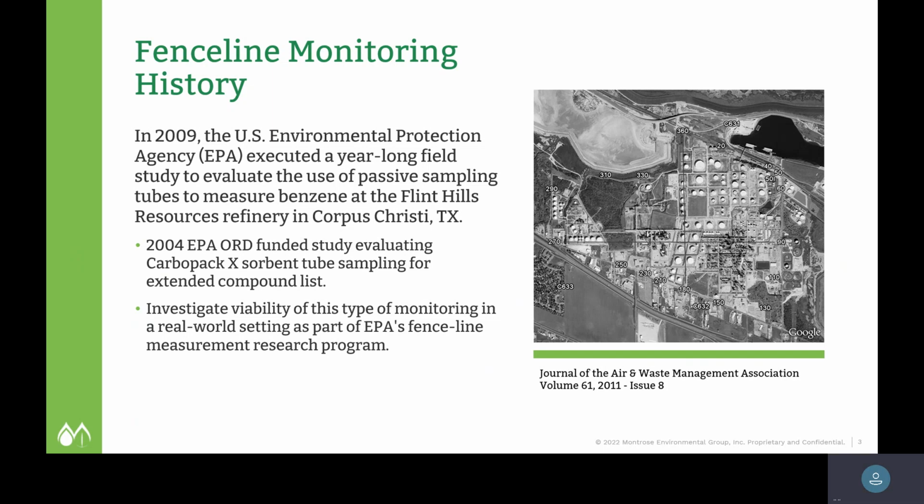One component that they put in place, which is pretty cool, is they deployed these passive samplers side by side with some auto GCs getting speciated benzene data. So you had hour-long averages of benzene speciated data that you would compare to these passive tube results for 14 days. So they deployed it for 14 days. The R squared was 0.86, pretty decent, especially considering you've got a time resolved application versus a 14-day integrated number. So really promising